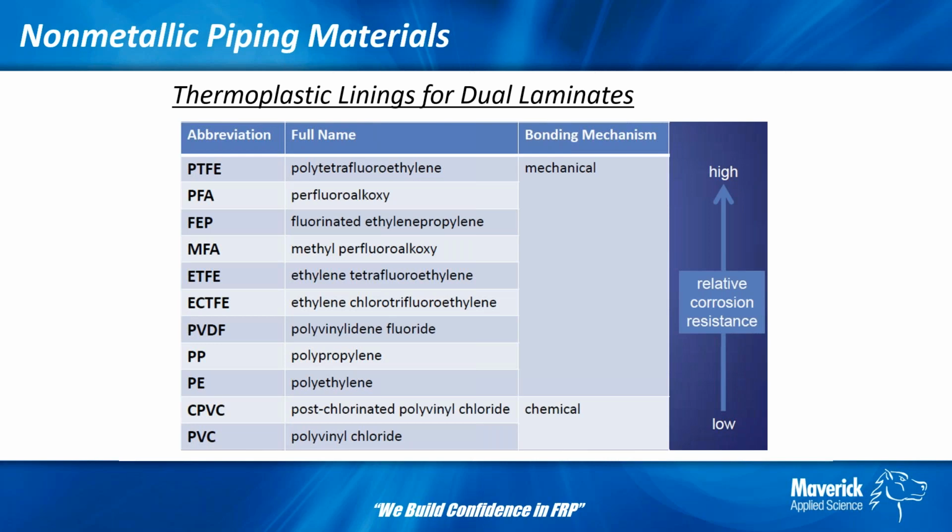I would say when you're inspecting and you see you're through the corrosion barrier, when you see that you're into the structure, whether you're doing borescope or, if we're in a tank, if you see structural windings, if you see the pattern of woven roving, for example, with that cross hatch pattern, when you can see that clearly and there's no corrosion barrier on top of that, or you're down to the very last mat. Generally you might have 2 or 3 mats, and you see spots where it is not there and you're into the structure.